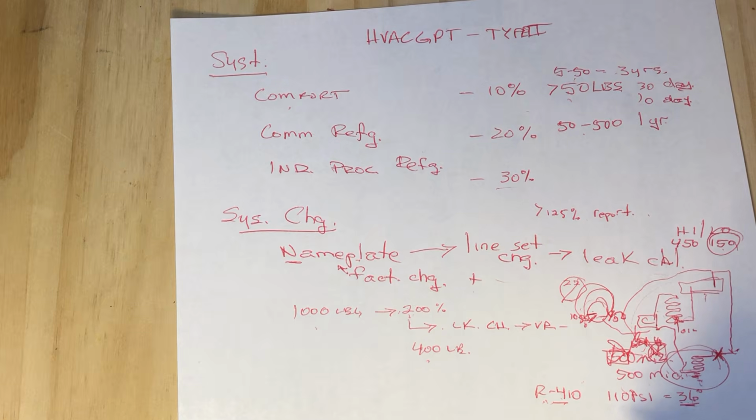and that will then be followed up with the liquid, because normally with any 400 series refrigerant we're charging and throttling it through the suction side as a liquid, but we would go ahead and start that off with vapor, and then any of the refrigerant that needed to be added would go in as a liquid. If this was a water-cooled chiller barrel, that would be for a very large one of these types of systems.